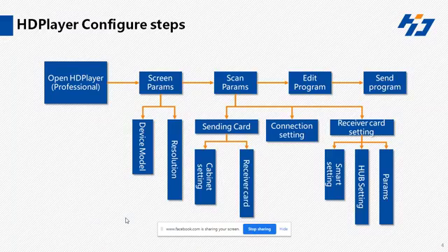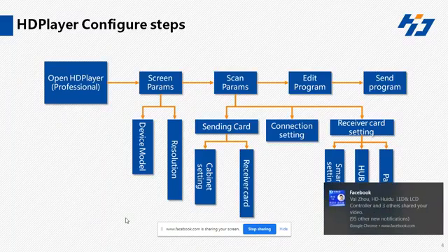I am again asking about the total width of the screen, not the total width of one module. Many people make the mistake here. You have to enter the total screen width and total screen height. The second thing is, after selecting the controller and your width, you press OK. Then after that, you have to go into the screen parameters.